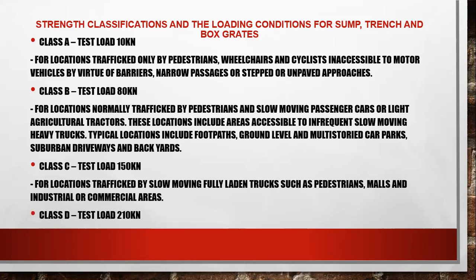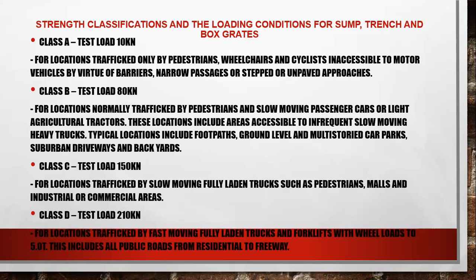The last is the class D. The test load is 210 kilonewton. For locations trafficked by fast moving fully loaded trucks, and the wheel loads up to 500. This includes all public roads from the residential to the freeway.